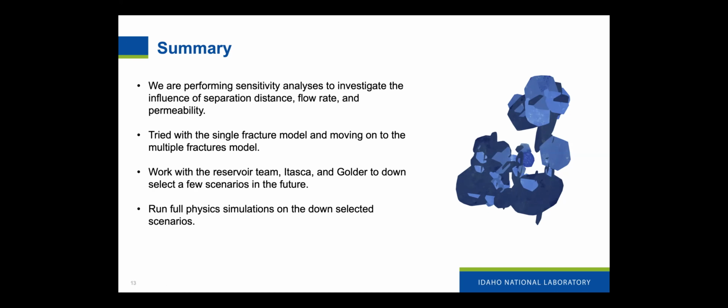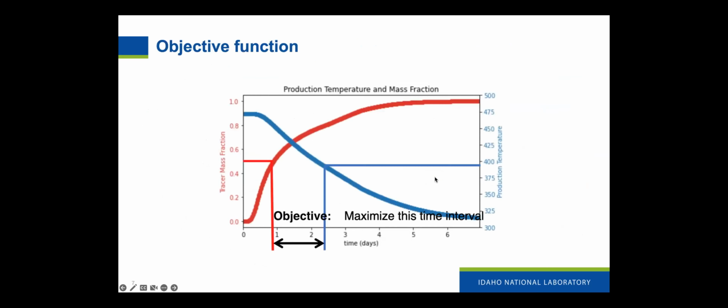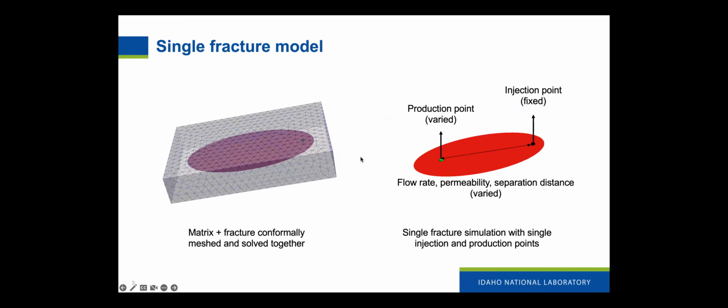Okay, so for the case that Sam showed, that fracture is essentially one contiguous mesh. It's a 2D plane, essentially a 2D domain mapped into a 3D volume, and they share nodes between the two domains. So it's essentially two matrix blocks. And that fracture is simulated using an equivalent porous medium type approach, with very high porosity and fairly high permeability. Surface areas are directly across the faces. The models share that area of the faces. So that's for that one.